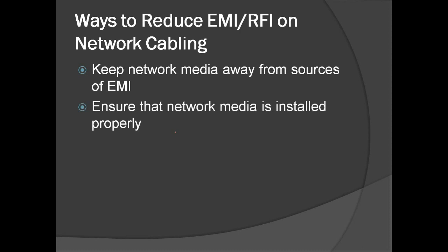If that is structured cabling, as much as possible use a PVC pipe to enclose the cable, or a cable tray to properly segregate the network cables from power cables or other cables in a building or location.